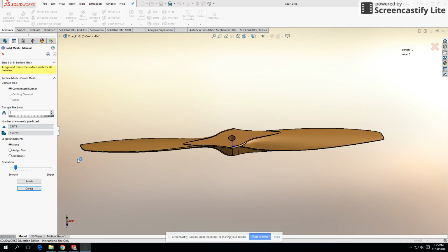So the most important part is going to be your mesh for your study. The mesh for your study determines how accurately your study runs and how long it will take. So if you make a really small element size, it's actually going to take a really long time. It could even crash your computer, but you'll get far more accurate results. So the key is to try and find a happy medium. Most people change their mesh in 3 separate increments, which validates your results, showing that they converge on a certain value. But you want to keep in mind to not go too small, otherwise obviously it won't run.